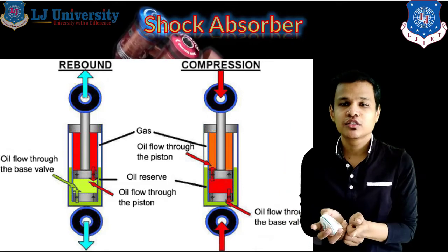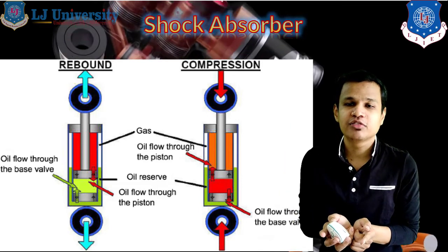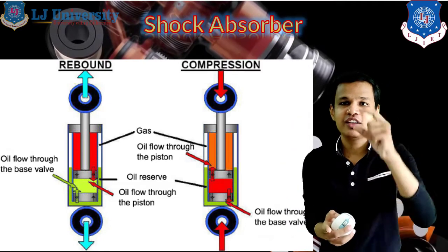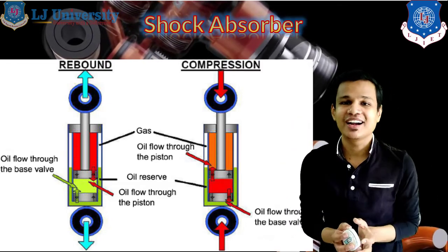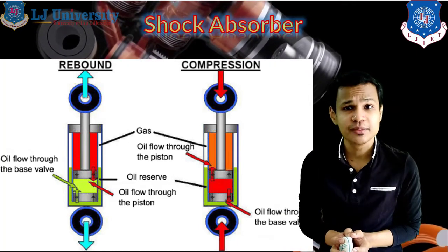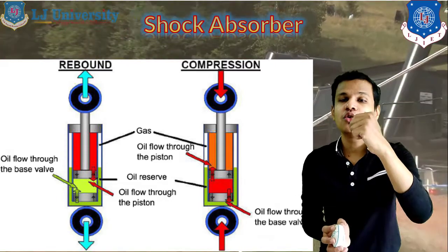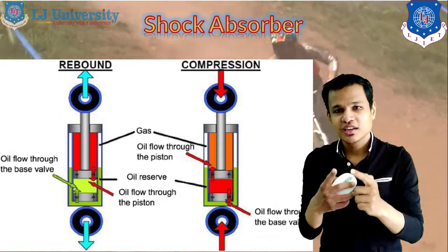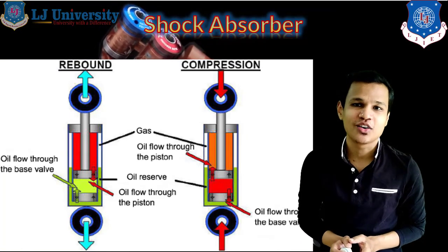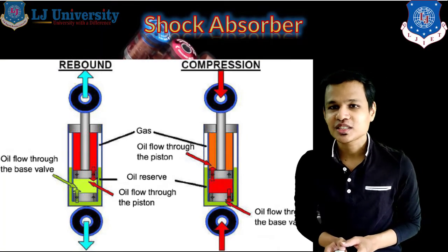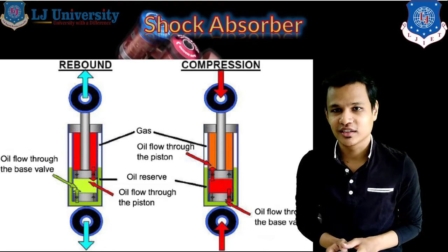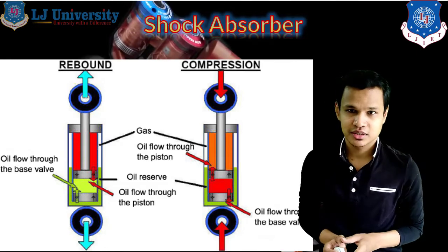The cylinder is of two types, twin shock cylinders. In the sideways path, we have kept some small areas where the oil is not filled. So that excess oil will go from valve B towards the downward side, then oil will be filled in the sideways path of the shock absorber. This is simply how our system works during the compression.